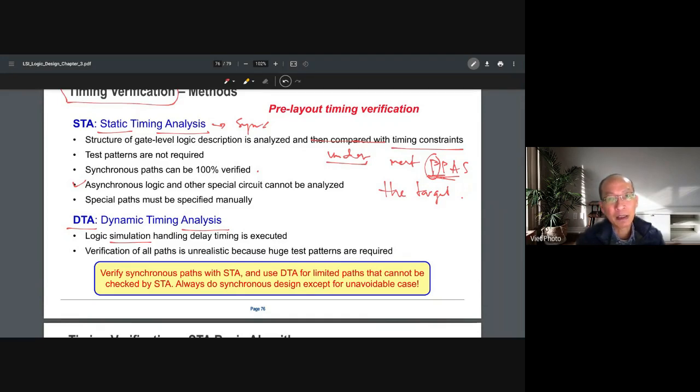The terminology is this: when they say the design has 10 gates, 1 gate is equivalent to 1 NAND, which is 4 transistors. But when we talk about an instance, the instance can be a NAND, a NOR, a MUX, an AOI, an AND or an inverter. So it can be a lot of things. That's why I said that 2 million instances is not 10 million transistors.